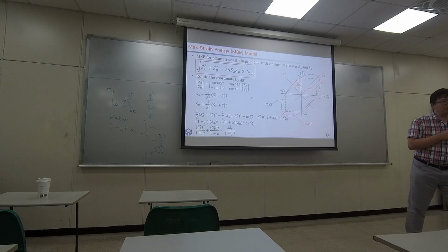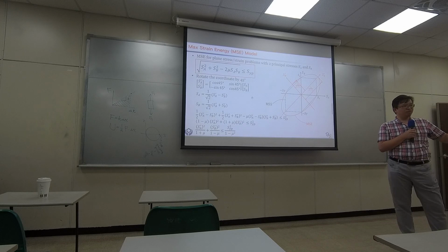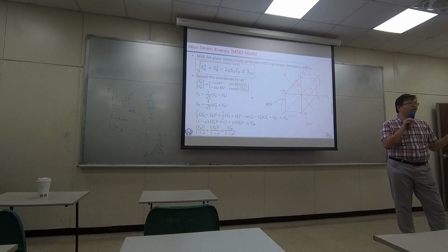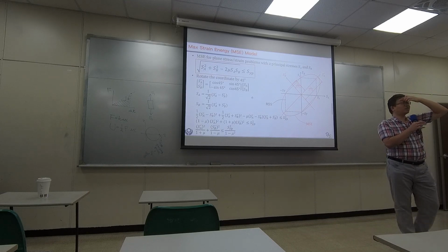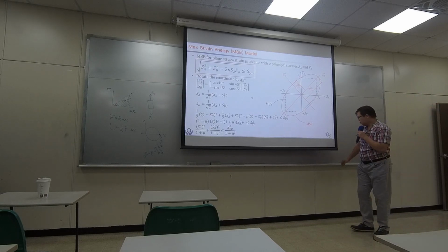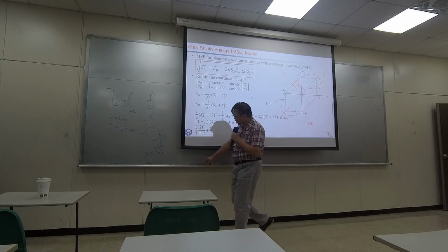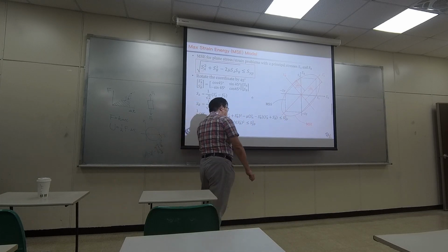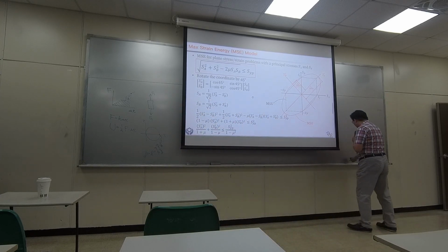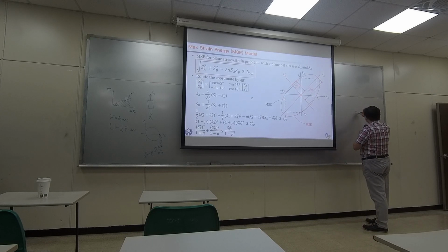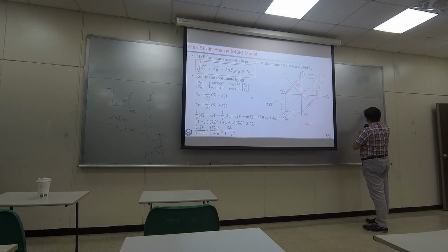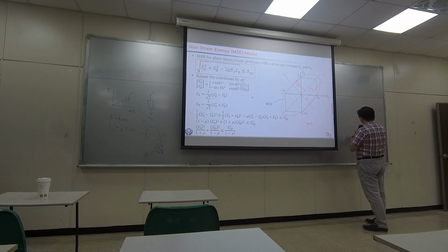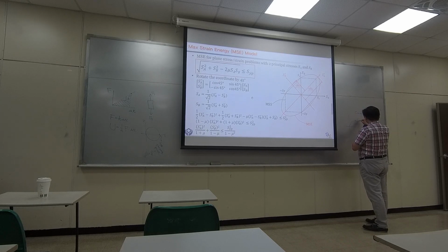So usually we only study the stress along the principal coordinate. We don't even care about what happened along different directions. That's why for the maximum shear stress model, we know the maximum shear stress for the Mohr circle is like half of your normal stress. If you have, here's your maximum shear, right?